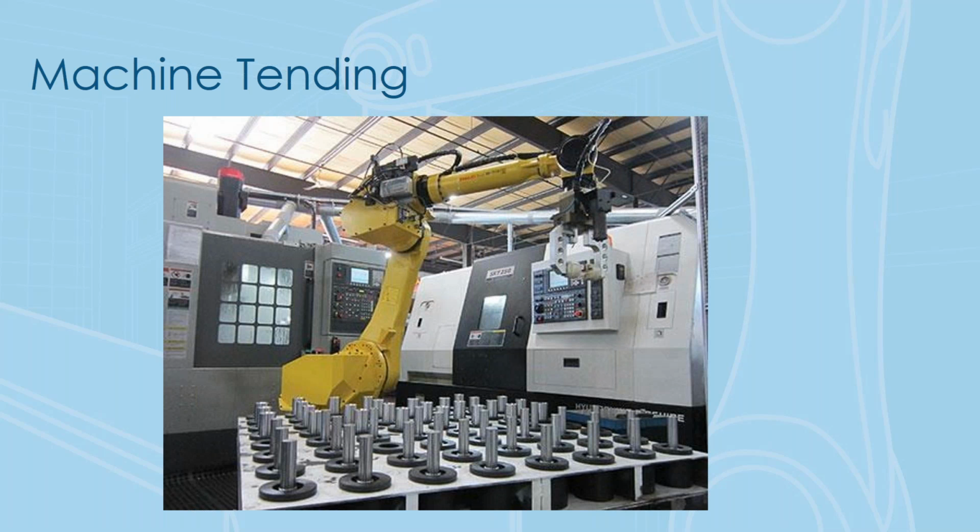Another thing on this image, and we'll get into this in a little more detail, is that if you are considering automating with a robot, one of the things to bear in mind is that once you've added that robot to your work cell, now you have to figure out how you're going to present the parts to the robot. Unlike a human operator, you can't just throw the parts in a bin. The human operator can pick up the blanks out of the bin and place them in the CNC machine. A robot typically will need some kind of fixturing, a part magazine, or some other method of presenting the parts to a robot in a manner that it can easily acquire each part reliably each time.